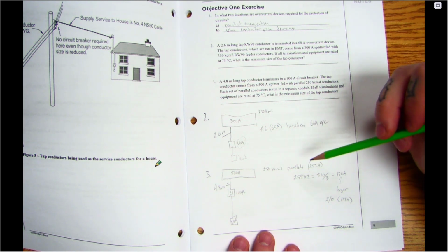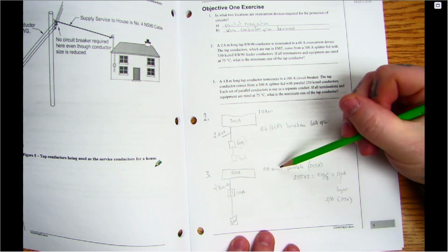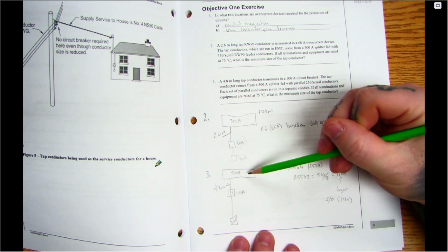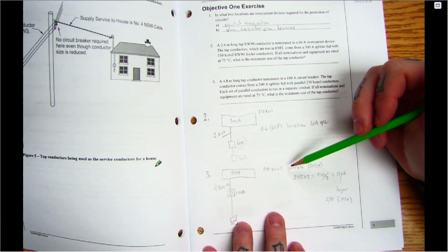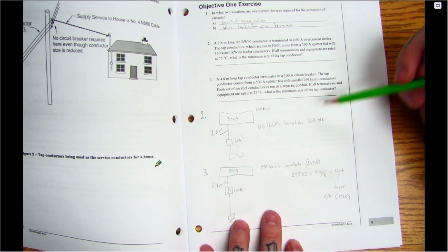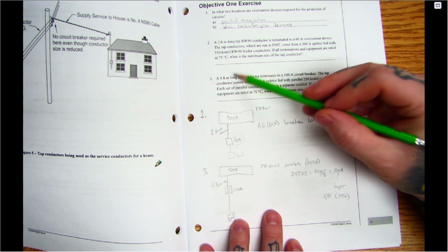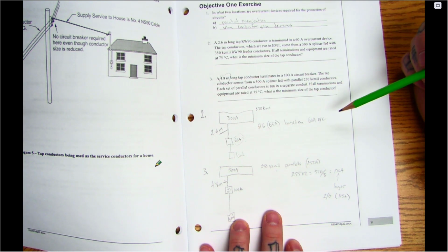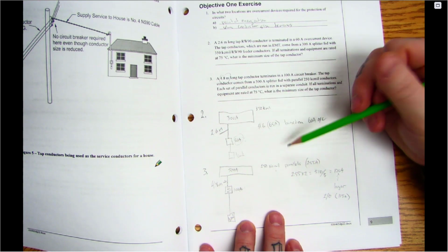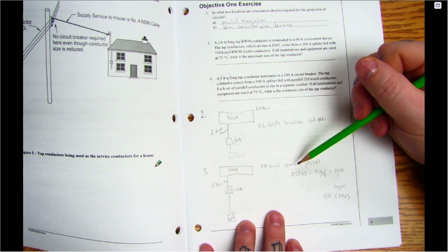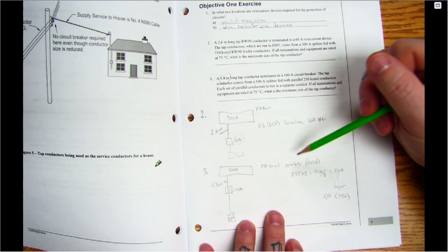Again, the rule says that we're taking 1/3 of the conductor ampacity. So don't get confused about the splitter rating. That has nothing to do with it. Just because it's rated at 500, that's not what we're dividing by 3. We have to find the conductor ampacity first. Since these are in the 4.8 meter section, we have to look at either the overcurrent device or 1/3 of the feeder conductor ampacity and choose the larger.